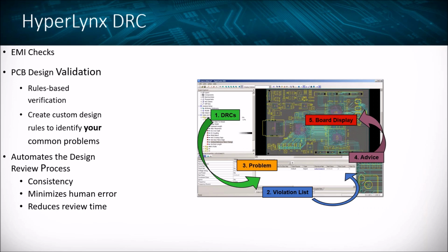Okay. So again, there are built-in rules in the tool, depending on your licensing level and how many you have access to. And in one of the licensing levels, you also have the ability to create custom design rules to identify the issues that you are most concerned about. What this allows us to do is set this up, adjust the tolerances or how the rules are checked, and create those as our schemes. This way you can use these to check multiple designs with the same setup.